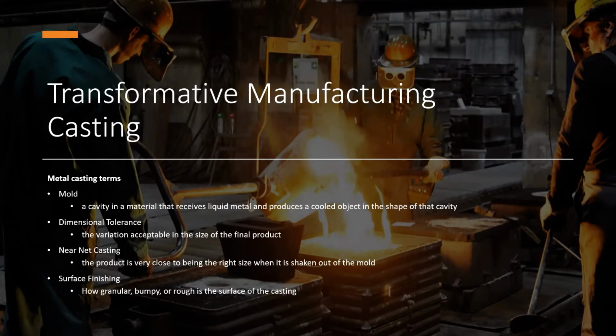Now you would think that that's pretty much what you want to achieve every time when you're casting, but near net casting is very expensive. You often have a lot of waste because you have to throw out stuff that does not meet the dimensional tolerance of essentially perfection. So you have to get rid of those. It's also a different mold creation that you have to use in near net casting. It's a different process, but again, adding cost if you're going to near net.